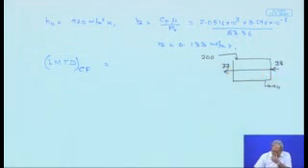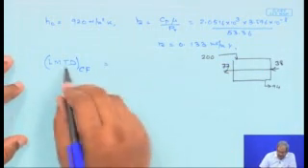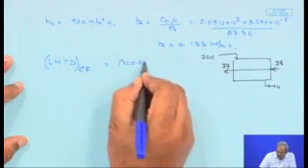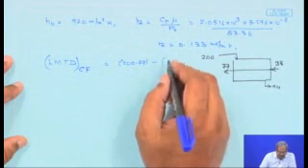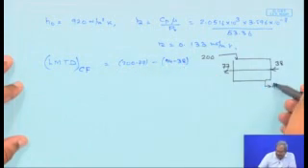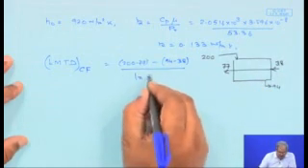So, this is the pure counterflow representation of the previous figure. Therefore, the LMTD would simply be 200 minus 77, which is the delta T at this point, minus 94 minus 38, which is the delta T at this point, by ln of the ratio.